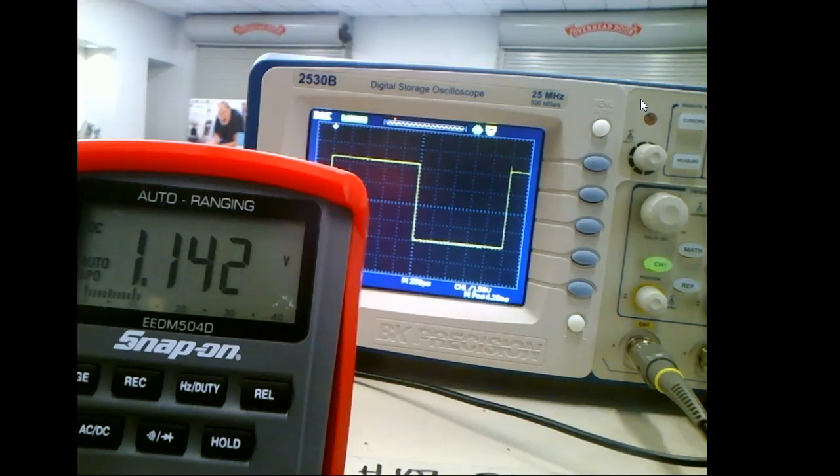What you would do is come in and use a digital input where you'd flip a bunch of switches and say, I want this thing to run at 200 RPM, and then it would do the calculation to run it. It could do it open loop, right? Open loop means we take for granted the speed the motor's running at, say 50% speed.